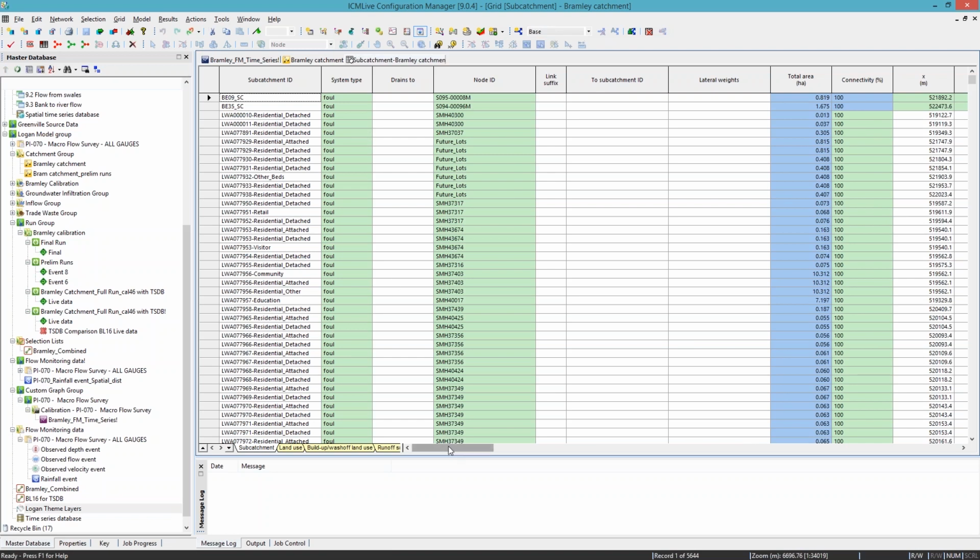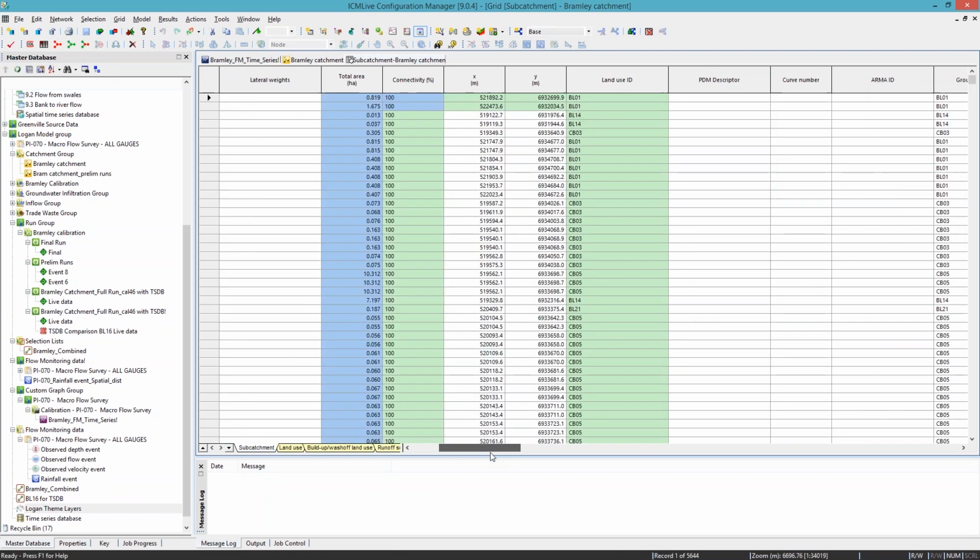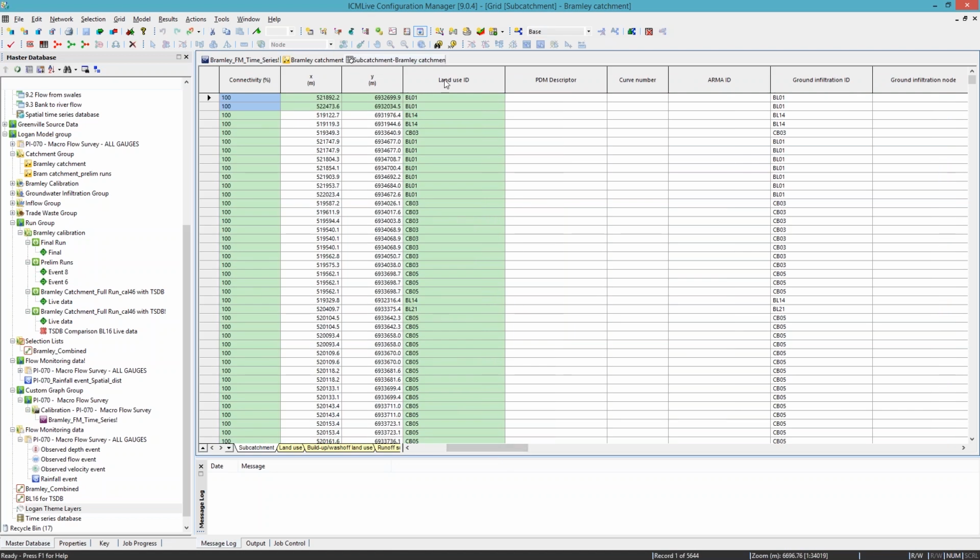We have land uses in there, catchment sizes. Usually our catchments are just the properties themselves. We don't typically include roads and those sort of things, just areas that could potentially contribute inflow and infiltration to the sewer. And there are obviously the direct property connections themselves. But in terms of the hydrology aspects, the key things to start with here are the land use IDs and